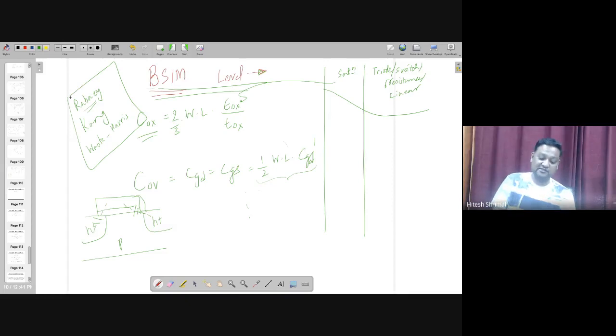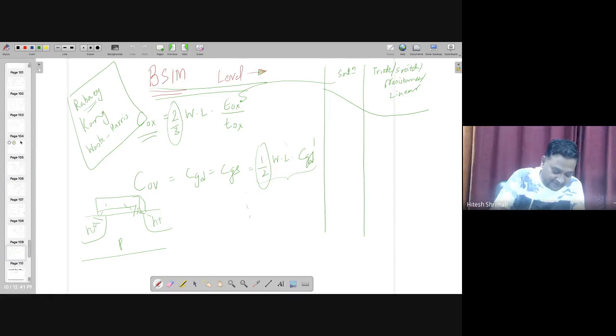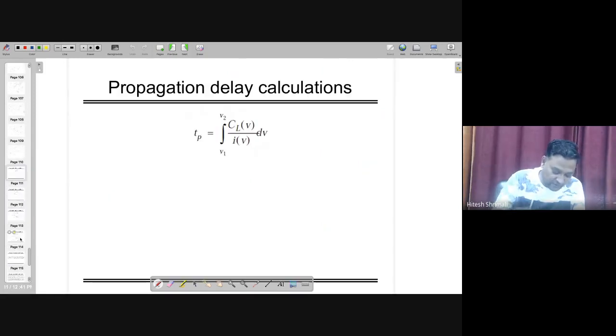With those equations, you can approximate the exact propagation delay, because sometimes it becomes multiplied by 2/3, or sometimes it becomes half. So those numbers will be useful. These are as good as fitting parameters, and they are followed in most of the books, which is why they have been given here. I believe you understand this capacitance, and you also understand that the propagation delay is equal to 0.69 times the path resistance times the capacitance at the node where you want to take it.